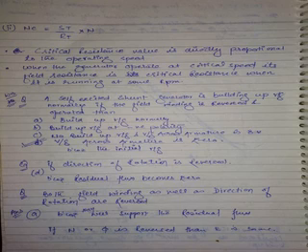If you operate above 900, it will develop. But RC depends on different speeds above NC. What is the critical resistance of the machine when it is operating at NC? It is nothing but its original field resistance. When the machine is running at its critical speed, you cannot increase the field winding resistance. Is the point clear? If you increase, it can't develop anything. What's the answer for question number 10? Simple. C, proportional. It is C.